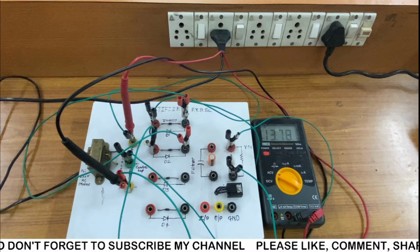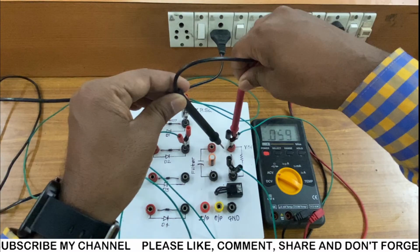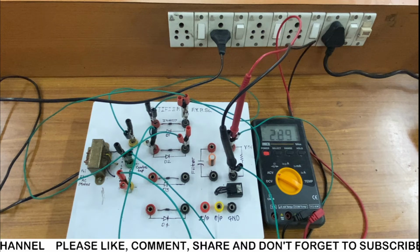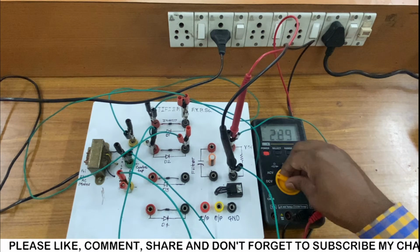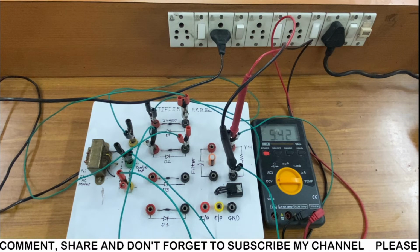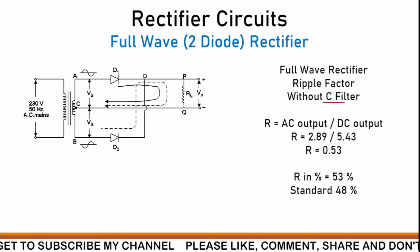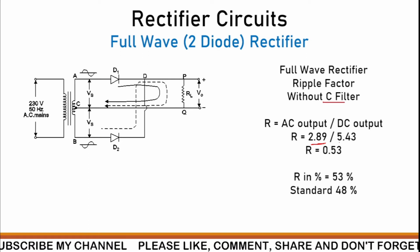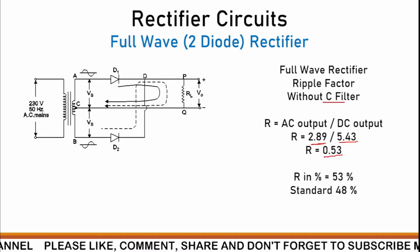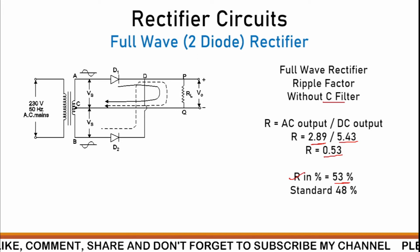Let's look at it here. I have connected the AC input, which is 13.69 volt. This is a two diode rectifier where we are using D1 and D2. I'm going to measure the output. The output AC is 2.88 volt and the DC is 5.43. From that we can measure the ripple factor. Without the C filter, we are having 2.88 and 5.43, so the ripple factor is 0.53. In percentage it is 53 percent, and the standard is 48 percent.